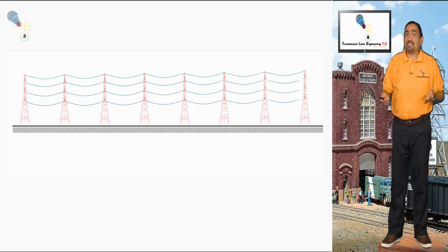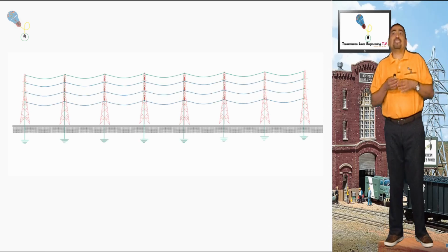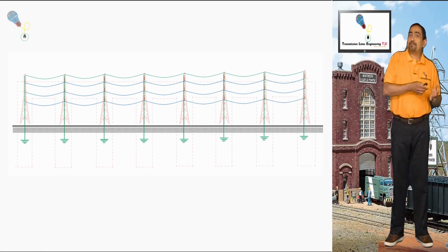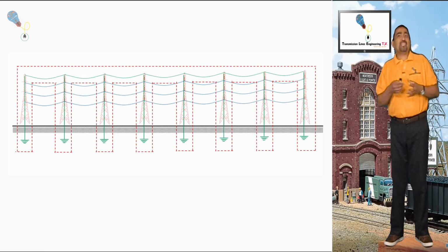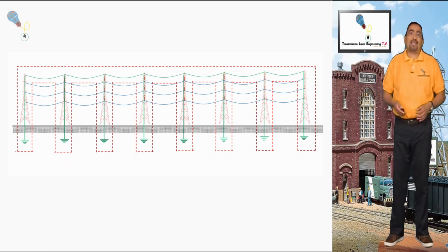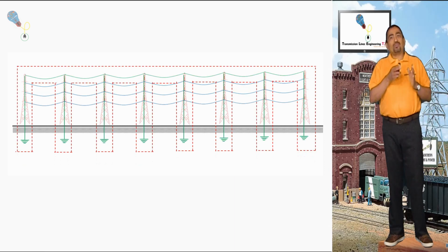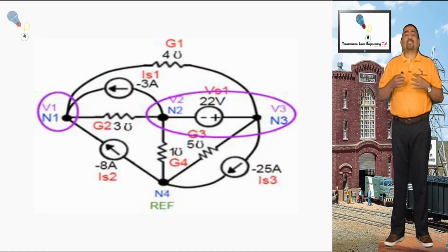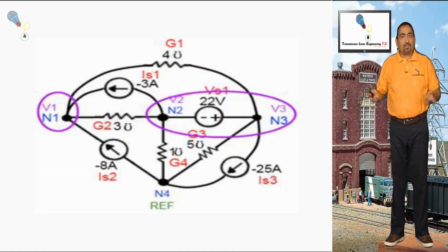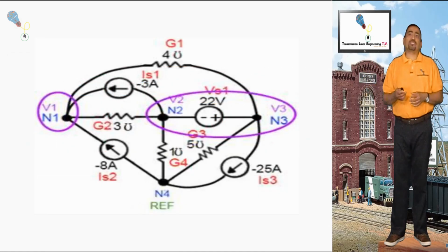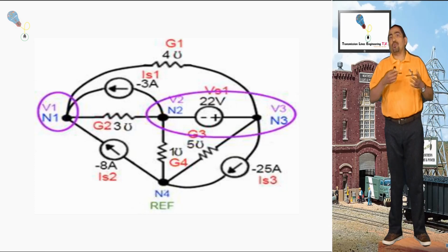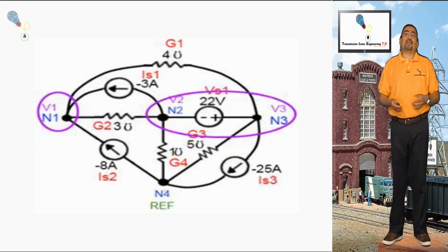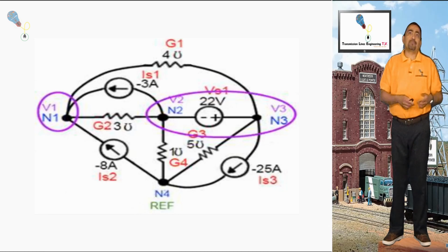Number 7, finally, the grounding system on the structures is a very important component, almost more important than the rest of the design, and it is the one which is least paid attention to, or we take it as the easiest one. The shield wire connects all the structures together, creating an electrical grounding supernode. You might have heard this concept of supernode if you studied electrical circuit analysis at some time.